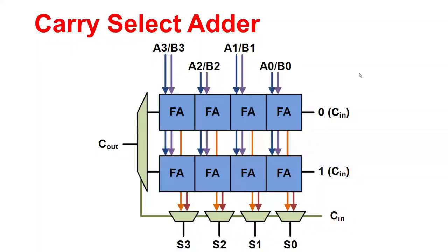All right, so welcome back once again, and we continue our discussion on the adder circuits in digital logic. So, in the previous module, we talked about the carry ripple adder, where we saw its operation and understood a drawback that it has, a delay problem. The speed of that adder circuit was low because the carry ripples from one stage to another.